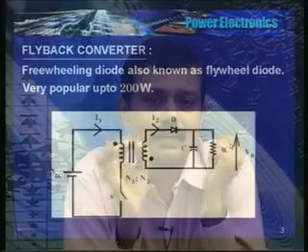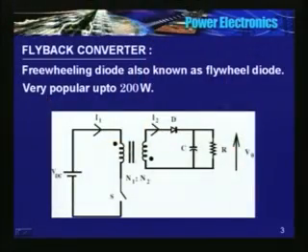It is very popular in power supply when the power rating is less than around 200 watts or so. So if the wattage of the power supply is of the order of 200 watts, invariably you can think that it is a flyback converter. Okay, very popular in low power range. Principle of operation is same as the previous one.